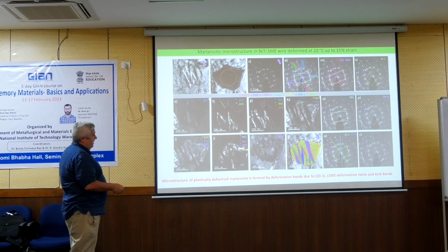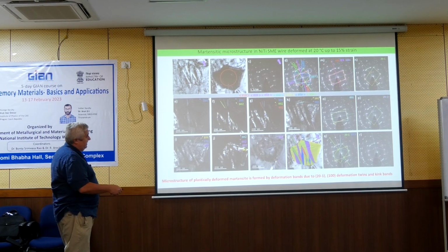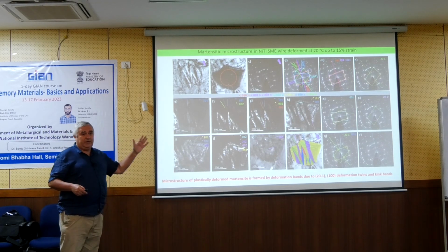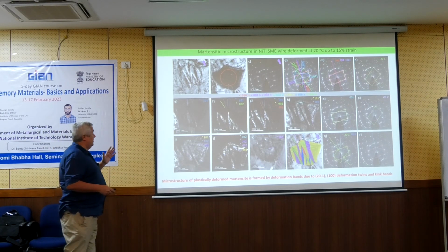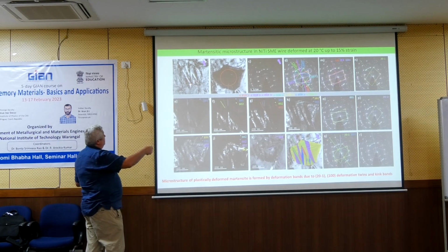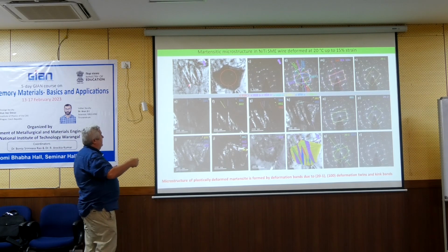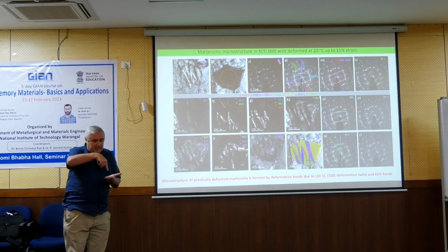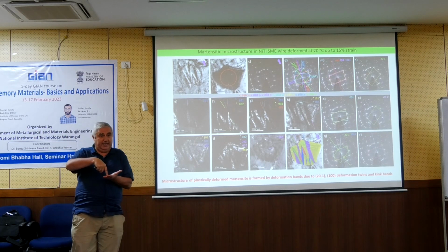Before, I have shown this microstructure only schematically, and this is the result of the analysis of the microstructure here. You can look into the paper to find out the details, but just to explain: I have selected some grain here, and I already know from the analysis before that I have to rotate the foil in such a way that the electron beam is aligned with the 010 direction.